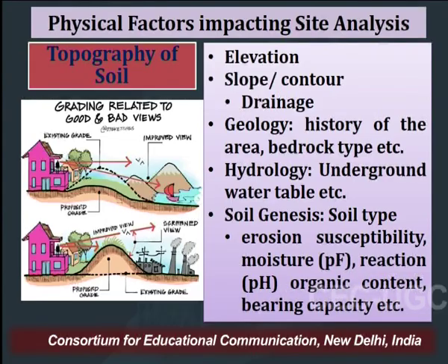Is it a shallow foundation system? Is it a strip footing? Is it a strap footing? Or do you need to go down deep till the bedrock to keep your building stable and go for pile foundation? So, the geology of the soil needs to be tested before going for the design aspect and deciding what type of construction technique has to be implemented. So, it has a very big role while doing site analysis.